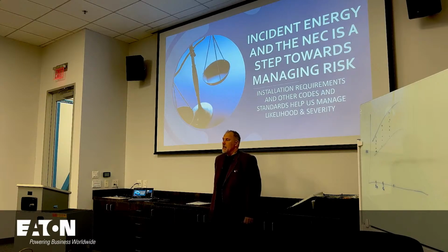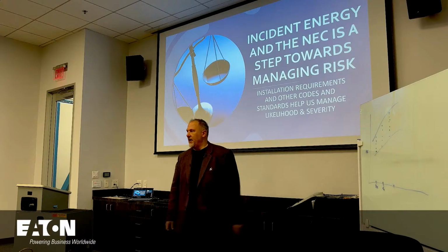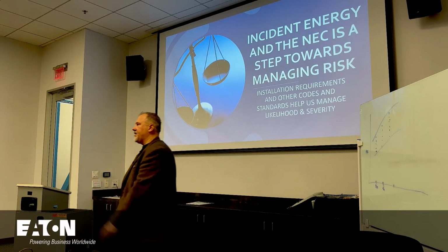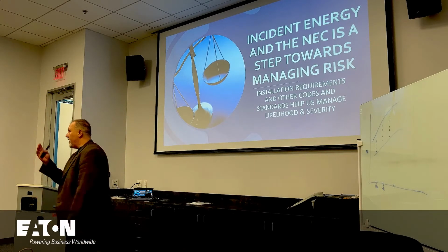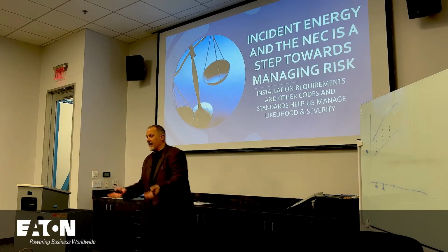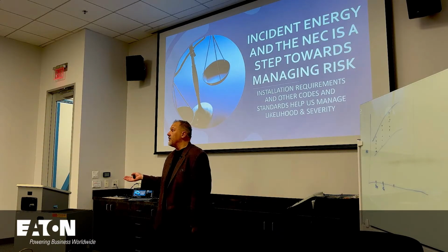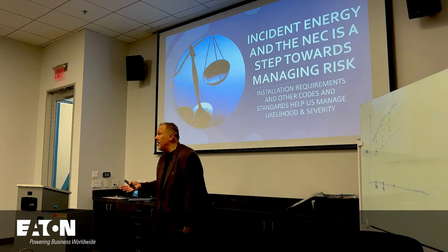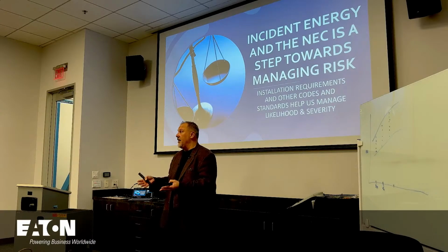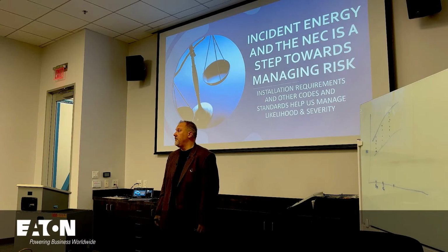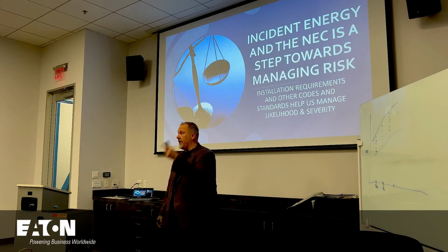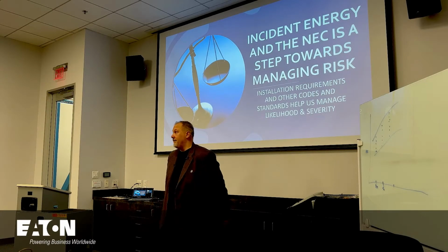No, you're right. Okay, and you said the right word there, the AHJ, whatever makes the AHJ happy. If he says he wants the date changed, then you're gonna have to change the date. But you have to make a valid argument to say, look, this is one of my calculations. The fact that I put it in on a Monday as opposed to a Tuesday doesn't change the calories per centimeter squared, doesn't change anything because everything else is exactly the same. I would make that argument with my AHJ and have the discussion, but if the AHJ says, nope, I want Monday's date on it, then he's gonna get Monday's date on it.